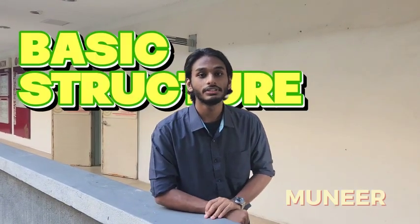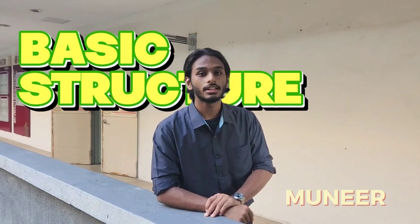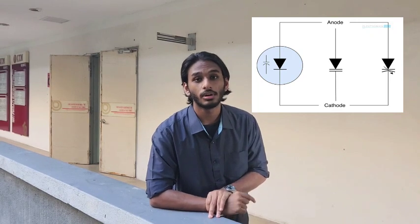Hello guys, so today for my part, I want to talk about the basic structure of the varactor diode. As we can see in this picture above, two molybdenum studs are attached at the bottom and also the top of the varactor diode. This will act as the cathode and anode for the diode.